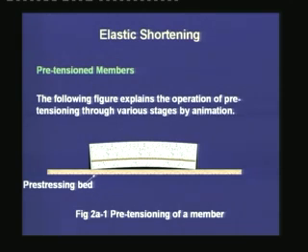If the tendon is placed eccentrically, then it will also deflect upwards, which is called cambering, along with the elastic shortening. That means in a pretension member, the elastic shortening occurs when we are cutting the tendons at the end and the prestressing force is getting transferred to the concrete. The system comes into an equilibrium after the elastic shortening.